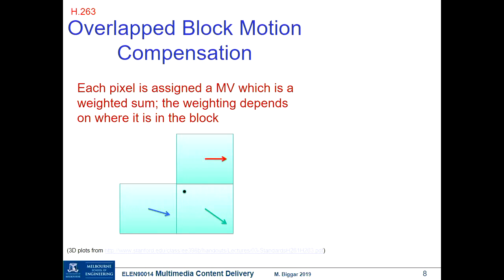So I really need to emphasize that we're not sending a separate motion vector for every pixel, but we are using these three, the neighbouring ones, or those from neighbouring macro blocks and the one that's associated with our current block, to calculate a motion vector to take a pixel from somewhere else in the frame used for prediction, and translate it to here to use it for the prediction.